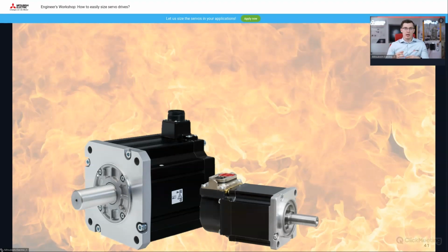Because the motor is warming up, and also the power output of the servo amplifier is warming up. If we could go too long with this overloading, then the motor could break, or most likely the servo amplifier would have a failure inside.